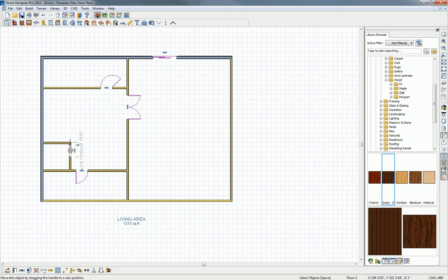And it looks like my door kind of moved around there when I changed that wall. So you can just select that, rotate that door, and move it up or down however you need to along the way. I'm also going to use that interior dimension tool one more time across through this room, and I'm going to make that a bit larger. Let's do 5 feet, 9 inches. There we go. Delete that guy, hit backspace on the keyboard, and we're set to go.